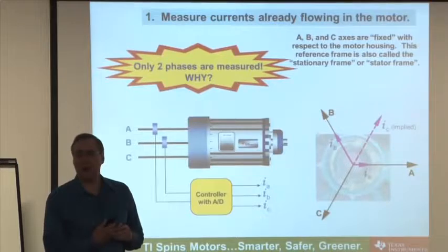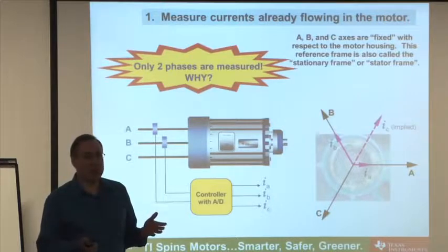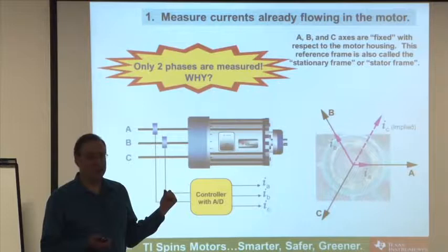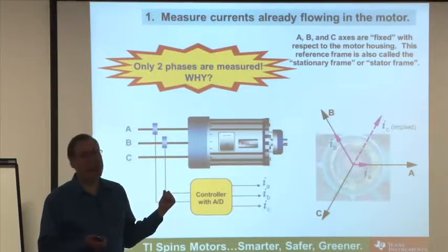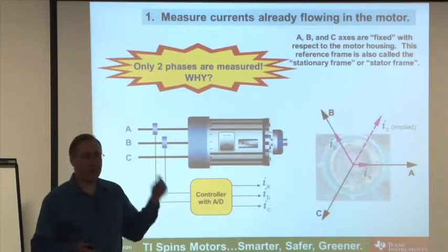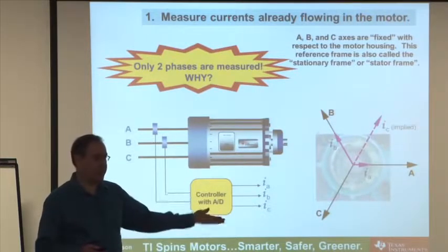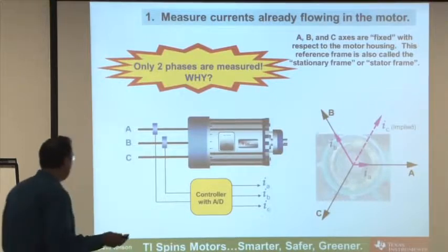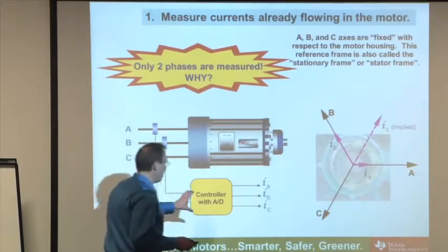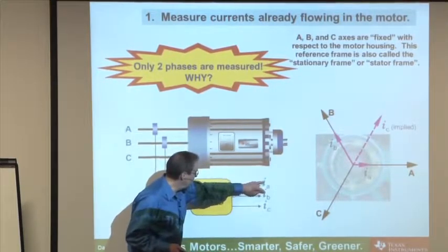Any guesses as to why? A lot of industrial motor drives will have 3 current sensors. Yes, both of you are right. If I have a winding to frame short, guess what? That law is broken, and then I can use my third current sensor to say, whoops, we are not seeing the right current. Therefore, you trip the fault light, bring the drive down to a safe state, and then flag the technician to say, go replace the motor.